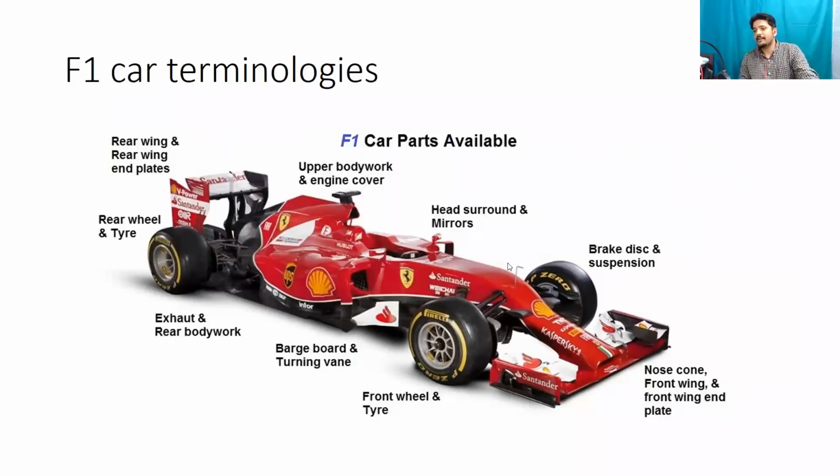Okay. Anyway, I'll let you type it, but basically, when you create a vortex, you are not only channeling the flow, you are also creating suction effects near the mid portion of the car. Now, one of the primary objectives of any aerodynamic design is that, at the end of the day, you need to slip through the incoming air as efficiently as possible. And one of the ways you can do this is by creating local depressions in pressure so that the air is pulled